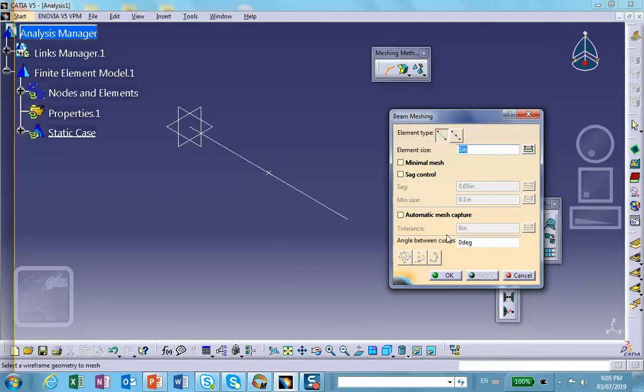So here's the situation. First of all, let's select the line. But down here, you see that there is this icon which says add isolated point. In other words, I have a point which is not on that mesh, not on that line, but I would like to include that to be part of that mesh basically. So you select this icon right there. See that? Select the icon.